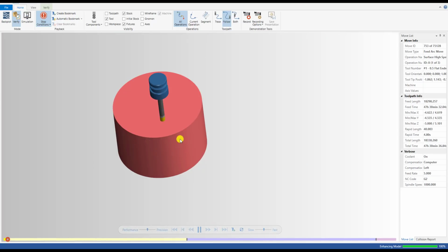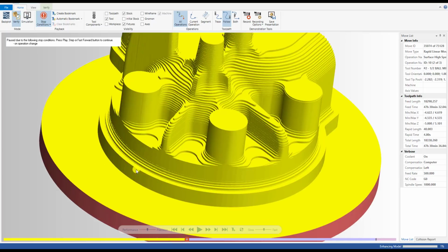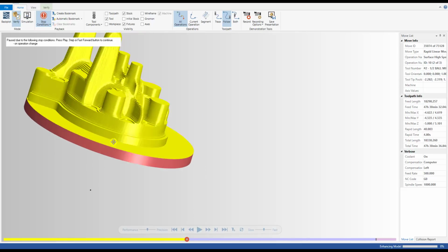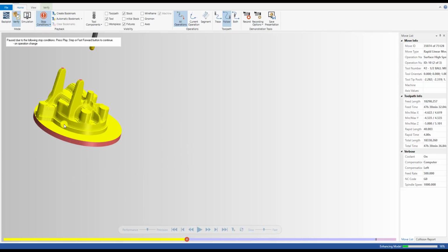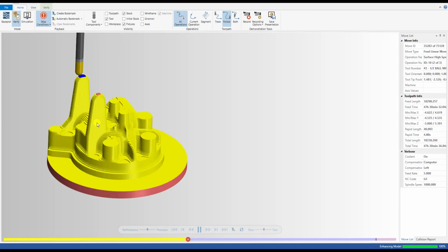we run the part. Okay, so this is the part after roughing. Yeah, be careful with this uncut material. You change the part and you also change here, so nothing had been cut here. So you need to make something like a sub operation for cleaning this material, like a 2D contour or something, before you're doing the finish. Okay, and now is the finish.